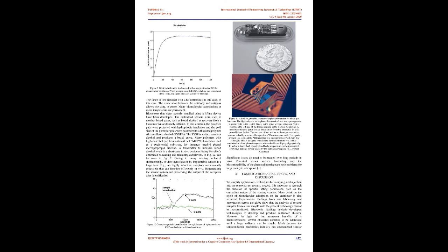Thiol chemistry is used on the gold-coated side of the cantilever to immobilize single-stranded DNA molecules, the DNA samples. The immobilization of single-stranded DNA results in a broad bending. Hybridization and further bending of the cantilever occur through a flow of single-stranded target DNA. Fig 5 shows cantilever bending with DNA hybridization.